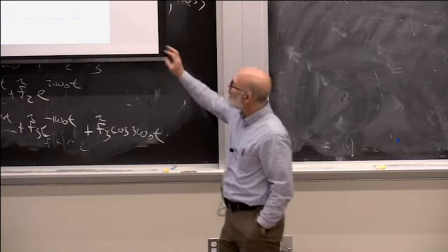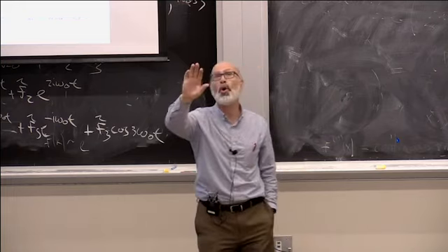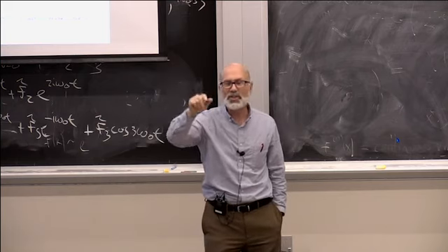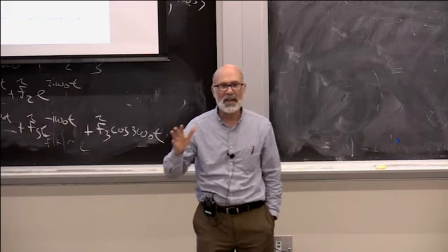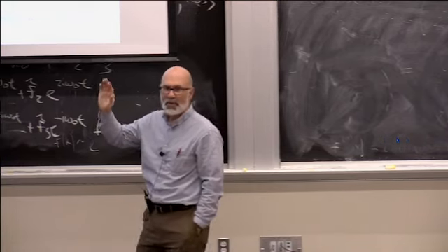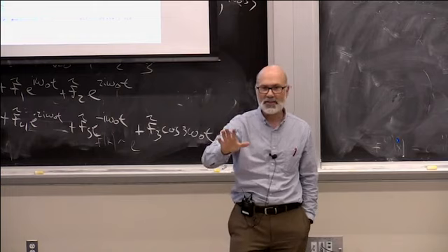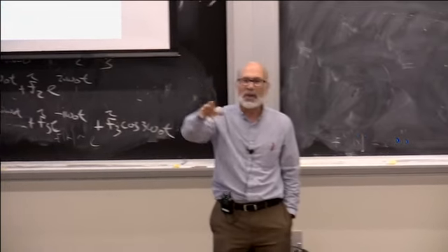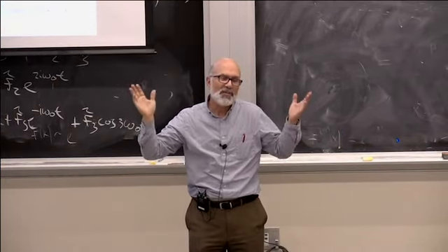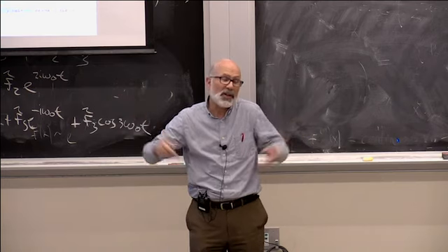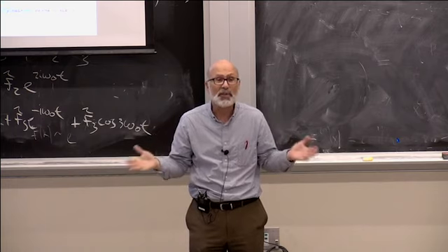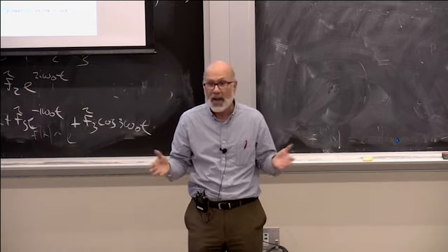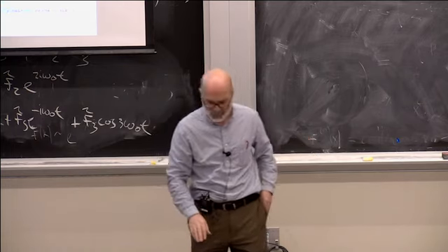No, this is not "let's hold the light red extra long." This is just "we won't give priority." That's all. So we're not deliberately holding the light red. It's just, if the bus arrives and the light is green, okay, bus, you get to go through. But if you arrive when it's red, I'm not going to hurry up and turn the light green for you if you're early. I'm only going to do that if you're late.